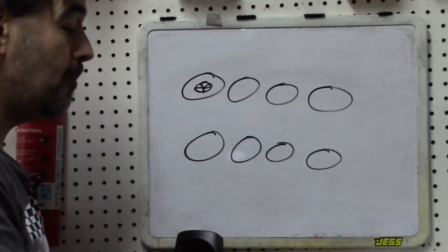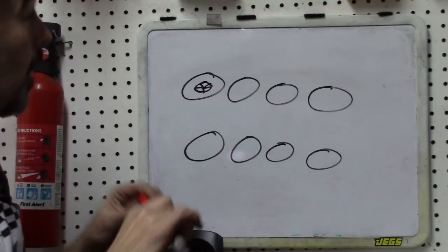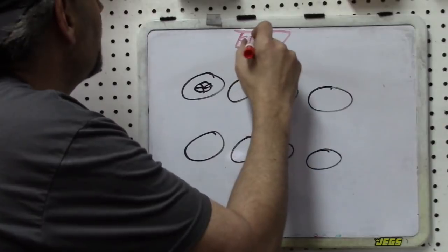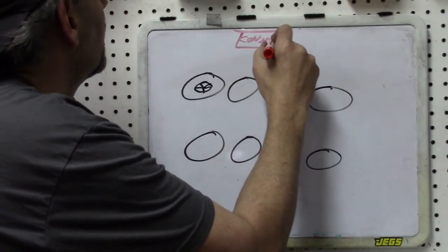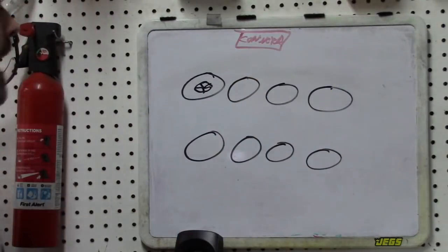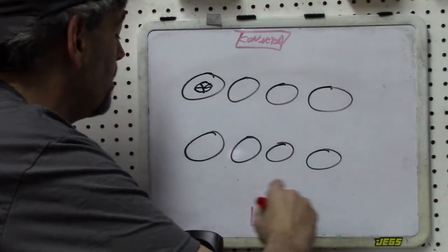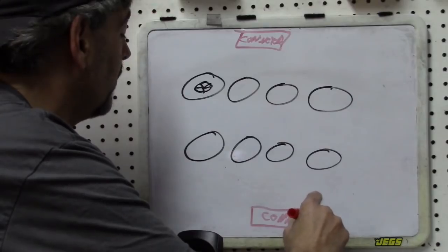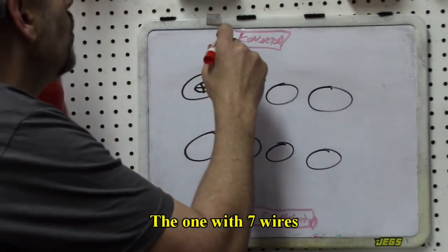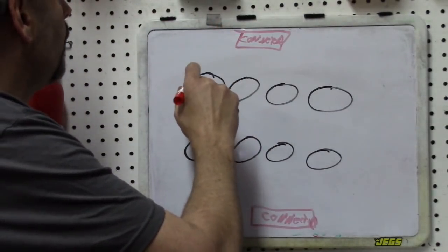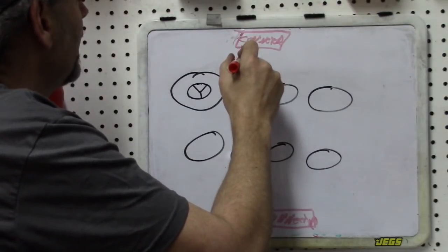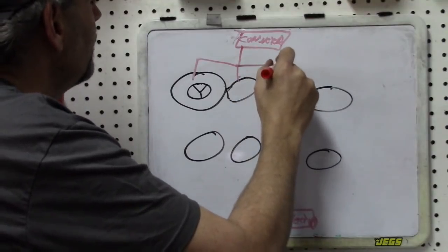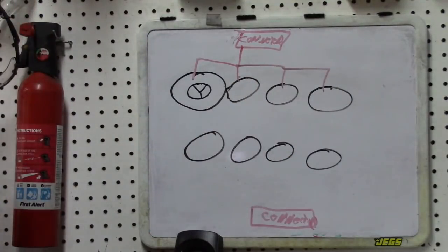We know we're going to have power feed. There was a red wire on that main connector. Here's our main connector up here. That's not the PCM. That's our main connector. There's also going to be another main connector here. It's that big white connector that we saw earlier. All right, we know there's going to be 12-volt power. This power wire is going to branch off like this and feed each of our coils.